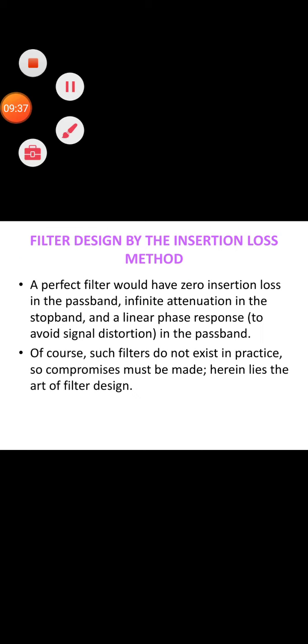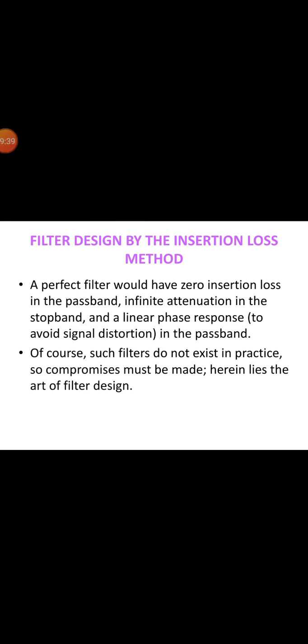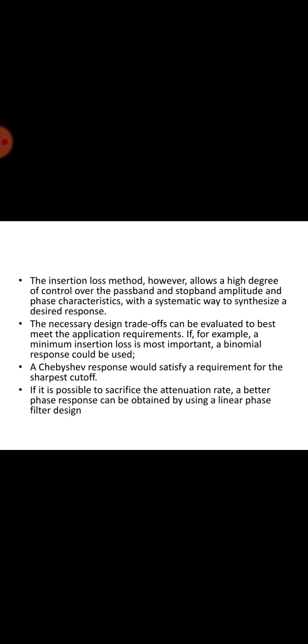And next let us discuss the filter design by insertion loss method. A perfect filter would have zero insertion loss in the passband, infinite attenuation in the stopband, and a linear phase response in the passband. Of course, such filters do not exist in practice, so compromises must be made. Herein lies the art of filter design. The insertion loss method, however, allows a high degree of control over the passband and stopband amplitude and phase characteristics, with a systematic way to synthesize the desired response. The necessary design trade-offs can be evaluated to best meet the application requirements.